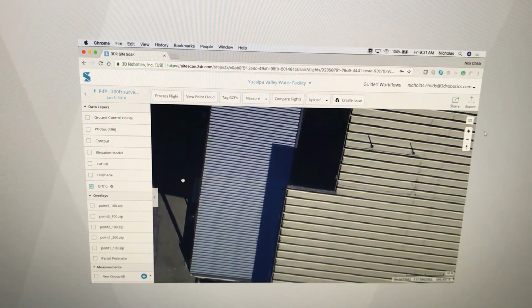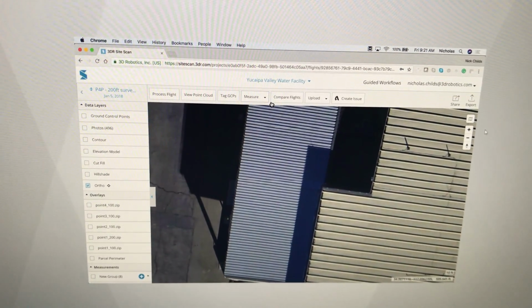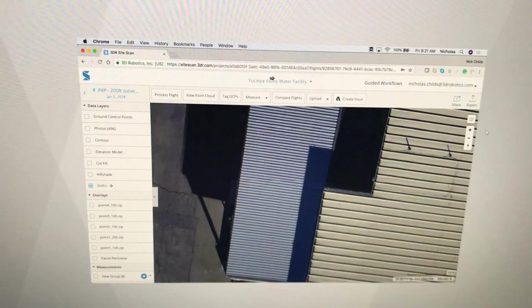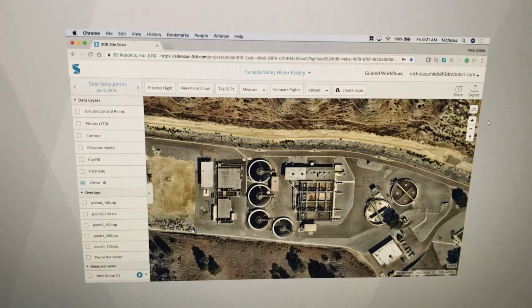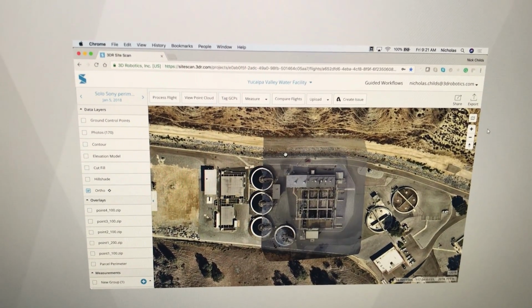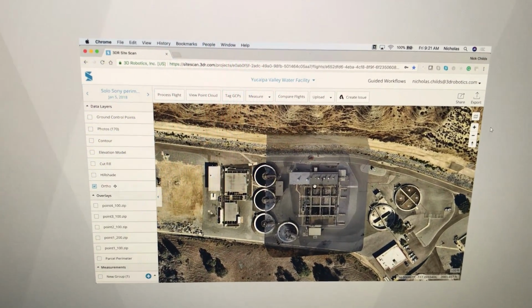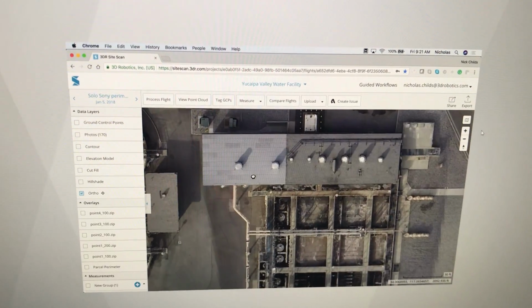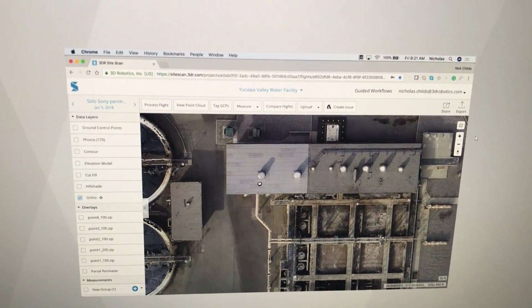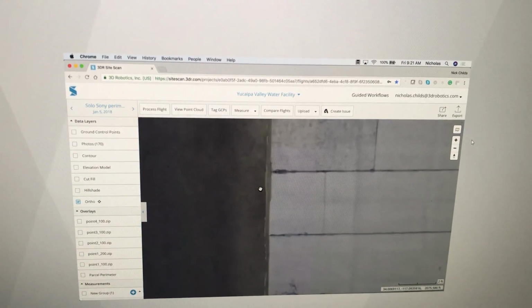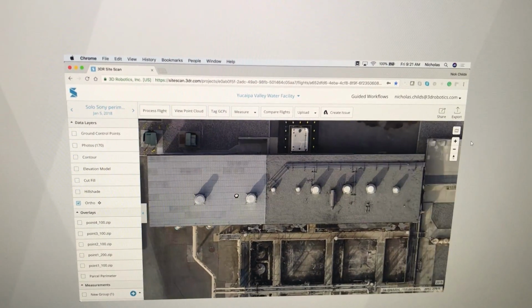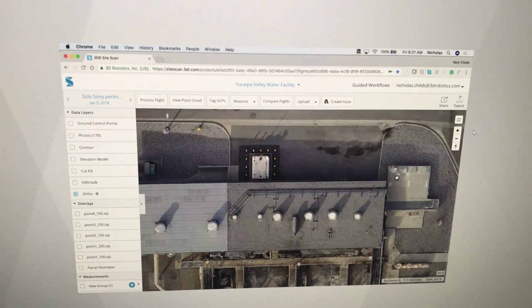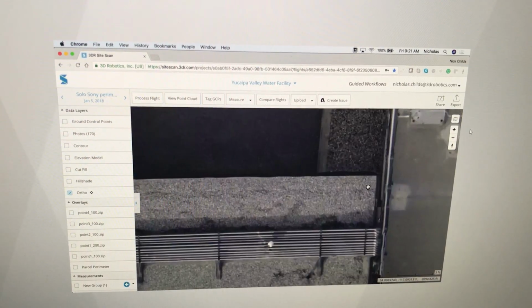Okay. So if the client wanted a really clear, really good looking orthomosaic, how do I go in and edit the edges of that building? Because you know how things get a little fuzzy and wavy on the edges of things. You fly with Perimeter Scan. Perimeter Scan doesn't really get that edgy, wavy, kind of melted wax look. Okay, well, because it's doing multiple layers.